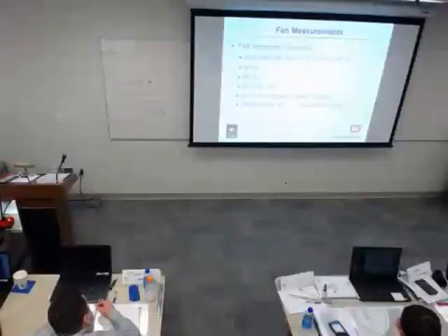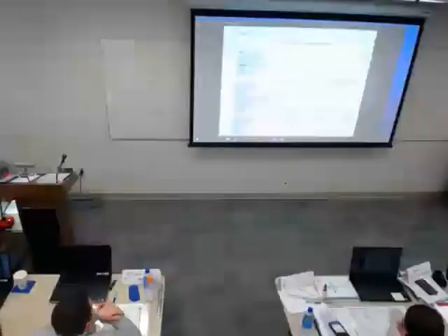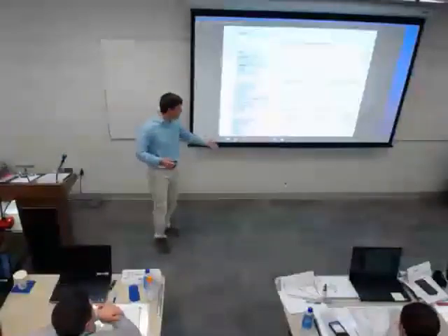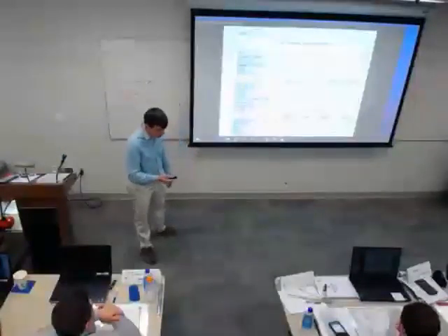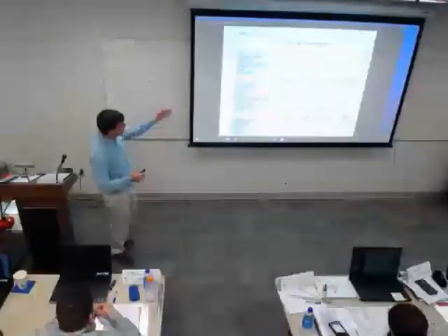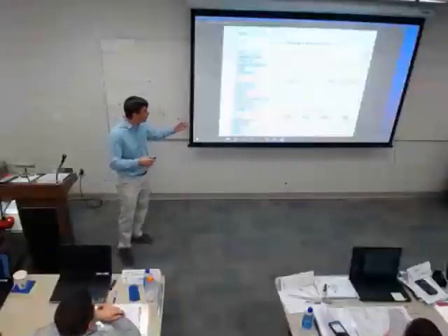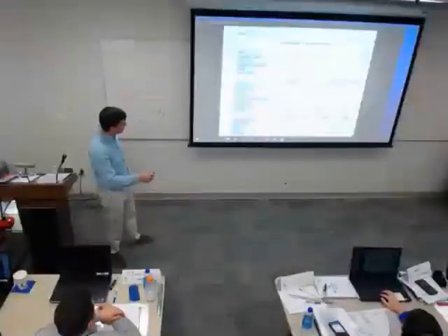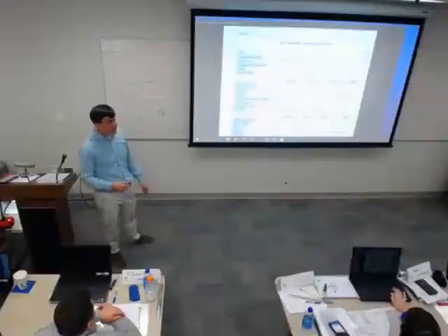Fan measurements. So what numbers do we actually want to get out of the fan? I'm going to shift back to another document real quick. This is what we're looking for out of a TAB contractor. We want to get some numbers for a fan. As you see, this is just an air moving equipment test sheet. This is a standard form that's in AABC. You can pull these up, I think these are online. They're standard forms, and at the end of the day, we want to get numbers for all this data.